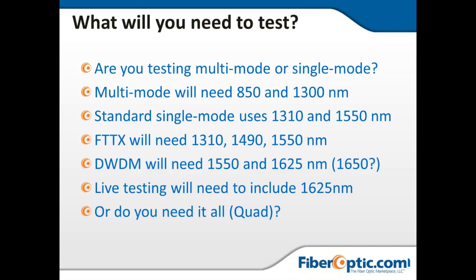And then the 1550 nanometer wavelength here is reserved for what's called our RF signal. A lot of the original television signals came with RF, so it's RF over fiber, and those were transmitted at this 1550 nanometer wavelength. So if you have a fiber to the home using RF over fiber, then you would use that 1550. If it's IPTV, then you might not need that 1550 wavelength, and you might just be operating at 1310, 1490. So just something to take into consideration if you've got a fiber to the home application: do you need to consider that 1490?